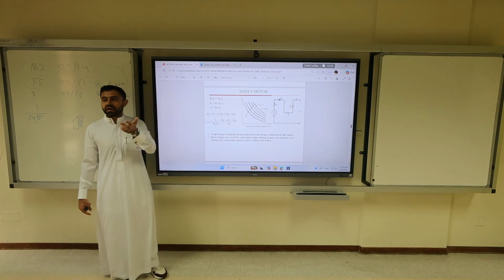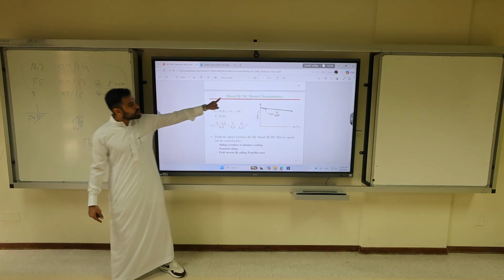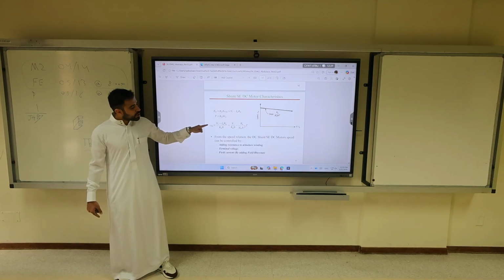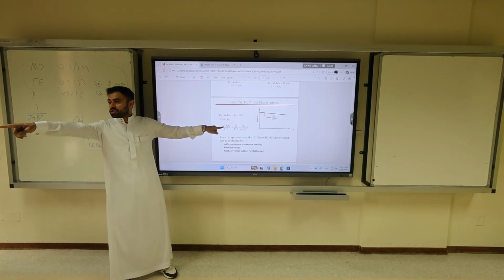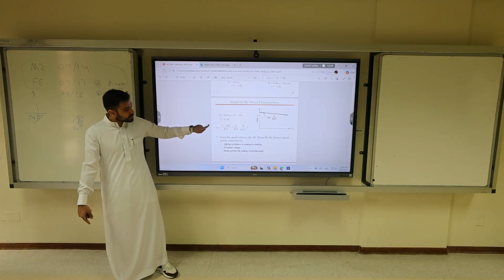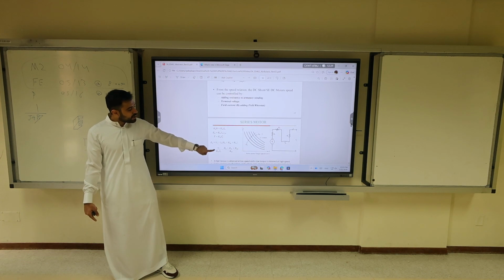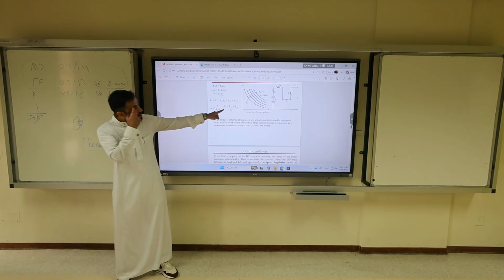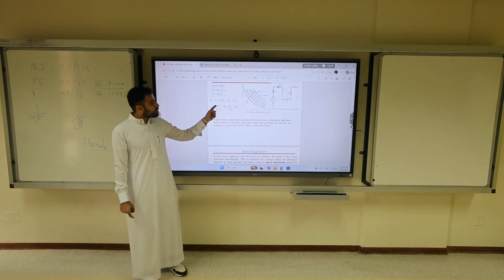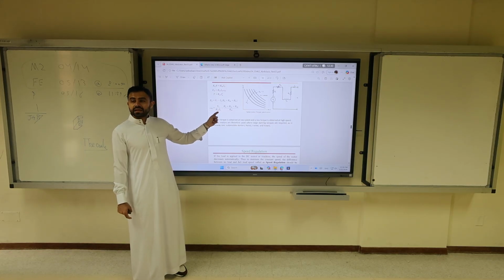So what do we learn? Controlling series motor is different than controlling shunt and separately excited. For shunt and separately excited, the equation is this one. You have to put it in the formula sheet. Where's the formula sheet? It's outside. Tell him to put it in the formula sheet. This is important. Also, the series has a different one. It is Vt over K times omega minus the summation of R's over the constant. So to control it, you either control the V or the R. But if you change V and R, you're going to also change the current Ia.